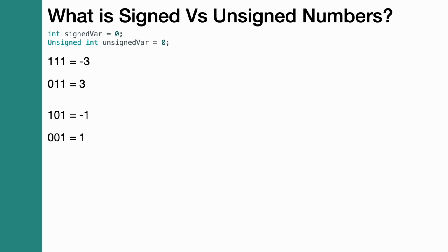So we're looking at the negative and the positive based off whether or not that first bit is set. So anyways, wanted to bring that up. I know it made for a little bit longer of a video, but I think it's important that you understand the signed variables for the embedded environments that you're going to be in, because they're going to become very important as you move through your development growth and maturity.